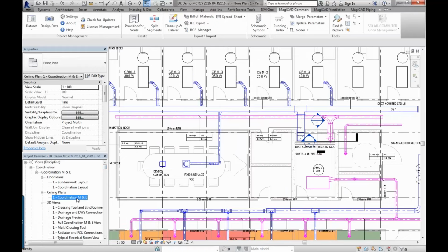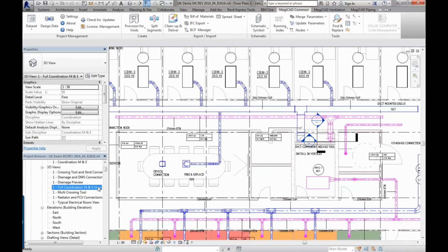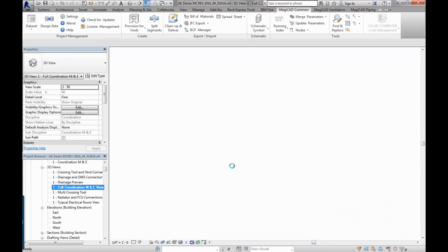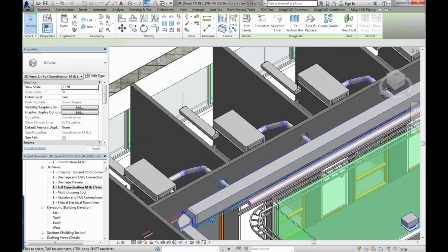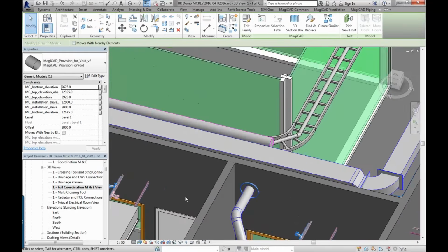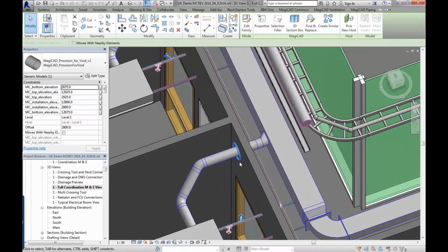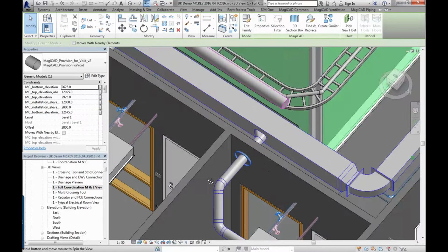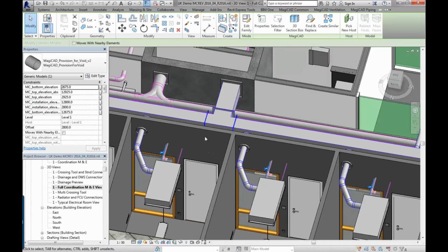voids in as expected with the automatic detection tools. And let's go to a 3D view here. You should be able to see the actual requests for the openings themselves. What they look like is cylinders or rectangular openings. So there's a family created into the architectural element there, and you can see that it's put the offsets in there. You can see how that works.